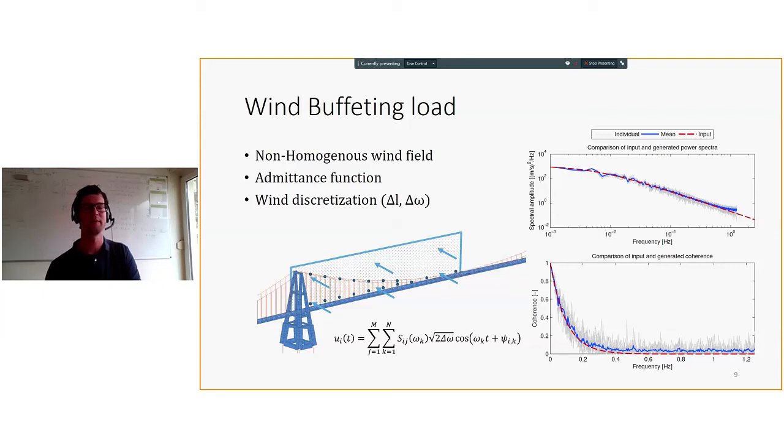By simply splitting the mean wind, which is logarithmically distributed, we then calculate the turbulence intensity based on a homogeneous wind field for some reference height, for example the deck, which is the most relevant participant. Then we can modify this turbulence intensity by the factor that should be modeled. So you can use a hybrid method where you calculate it homogeneously because of the numerical problems, and then try to match the actual non-homogeneous result. That was one of the ideas, and it's up to the user to decide.